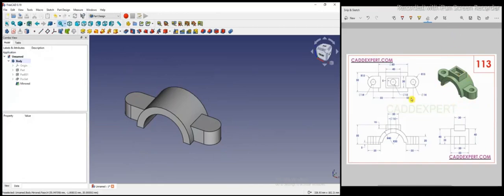Now we will make this pad feature. This is the top pad, this we will make, and its dimensions are given here. But if you see from the bottom edge, it is 50 here. Okay, so we need to draw a plane here, and then we will extrude up to the face.